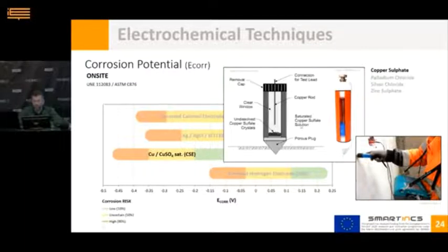Here a polymeric pod is used, and the porous membrane is much stronger. This results in a robust electrode that can be used comfortably and without risk of breakage for field measurements. Okay? The only requirement of these electrodes is that periodical maintenance is required to check and replace, if necessary, the internal solution.